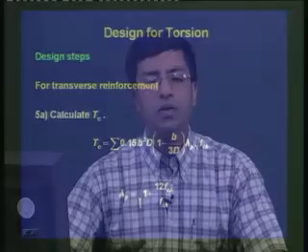Last time we saw that the capacity of concrete is based on the generation of a torsional crack at the mid depth of the longer side. If it is a flange section, then the expression considers the flange section as a compound section made up of several rectangles, and we use the summation symbol.